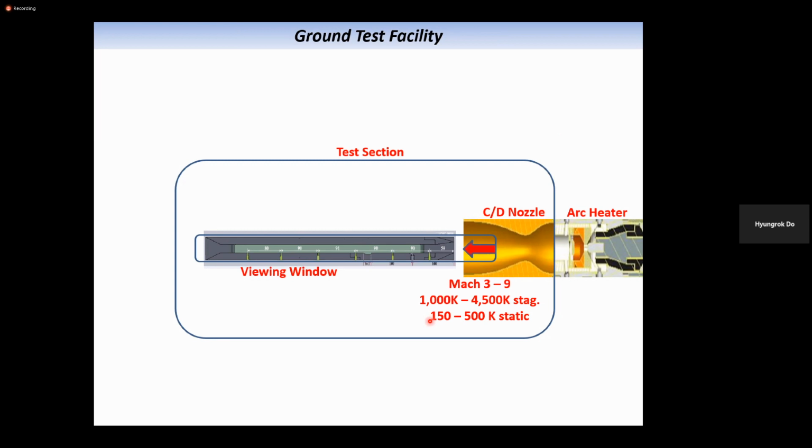Your sensor speed should be at least megahertz. 1 megahertz corresponds to 1 microsecond. Even for 1 microsecond, your gas is moving a significant distance. For optical measurement, as I said, you need only 100 nanoseconds. Then your gas will be almost standing still, so you can conduct quantitative measurement even with these high-speed flows using laser diagnostics. That's why you need laser diagnostics.